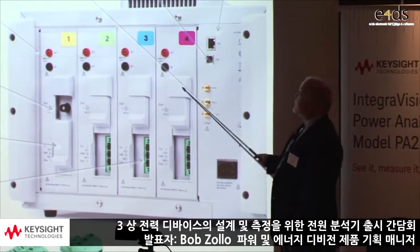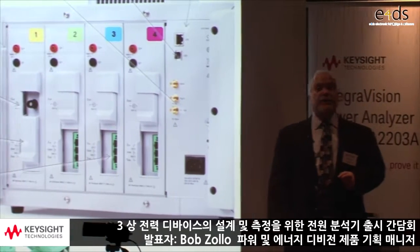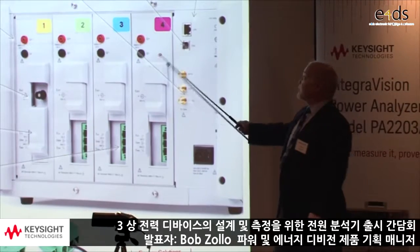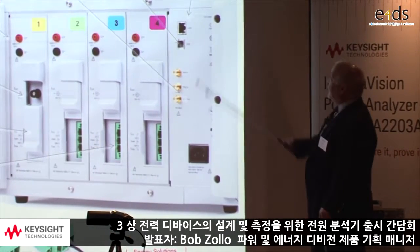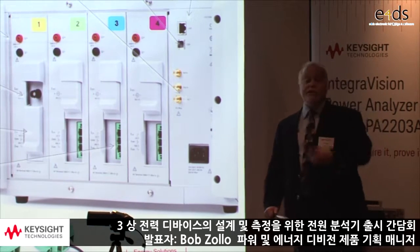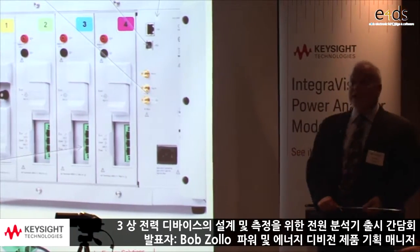It also has a trigger input and a trigger output. You don't normally find those on a power analyzer, but because we have single shot measurement capability, having a trigger signal is an important feature to have. And it can be controlled over USB or LAN for remote control. In fact, when we do a demo in a few moments, we'll actually be controlling the power analyzer using LAN capability.